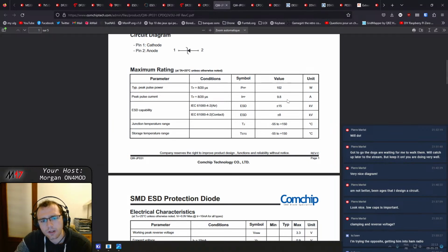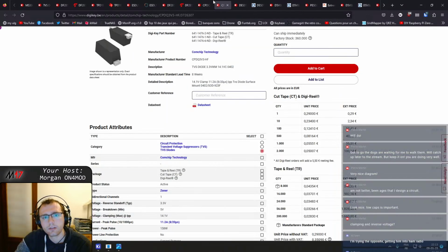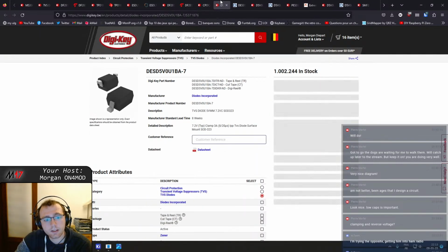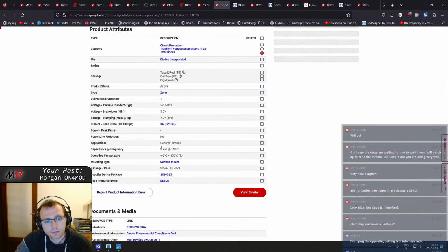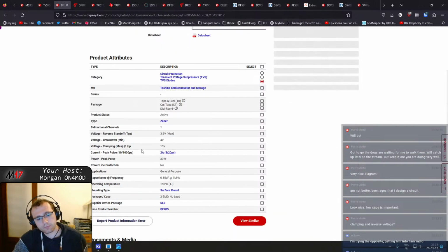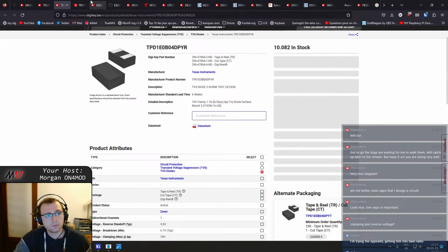Yeah, that was one that we were looking at. Oh yeah, okay, 80 picofarad, so it's way too much. 25. Okay, so SL2, it's too small. 0402, it's great.